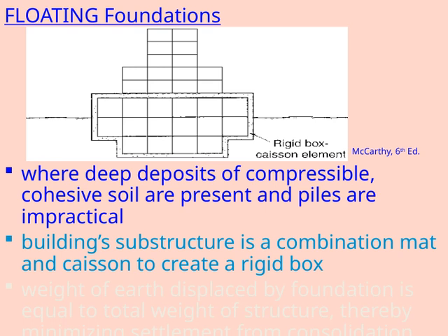The key idea here is that the weight of the earth displaced by the foundation is made to be equal to the total weight of the structure. This balance minimizes settlement caused by consolidation over time. This concept is from McCarthy's textbook, 6th edition. Overall, floating foundations are a clever solution when dealing with challenging soil conditions, ensuring stability while managing settlement effectively.